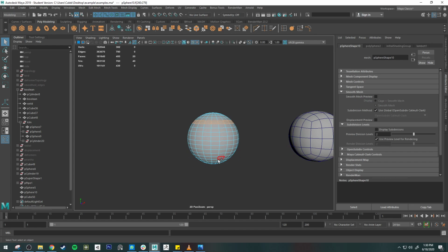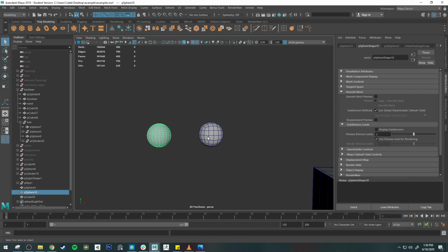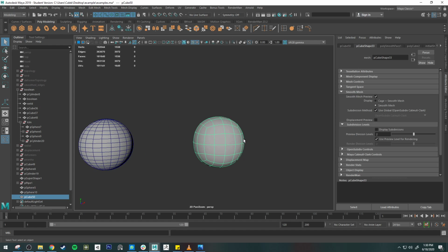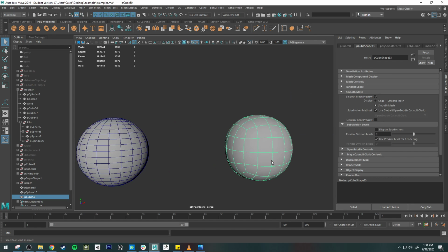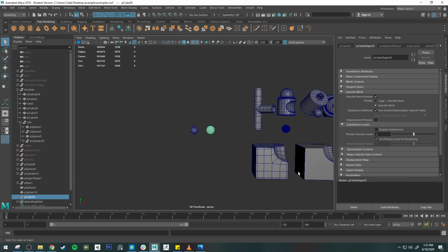I'd say if you need part of the mesh from like here to here, right, in between these areas where you're just having these radial up and down, left and right edge loops, cylinders and spheres work awesome, right? If you're going to be worrying about all the way around, or you're going to be having a cut on, or you have to worry about a corner and you just need these edge loops to still line up with your object, then using something like a cube, or another option, would be a good choice.